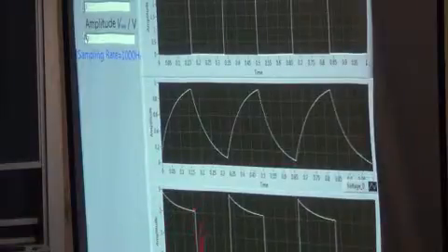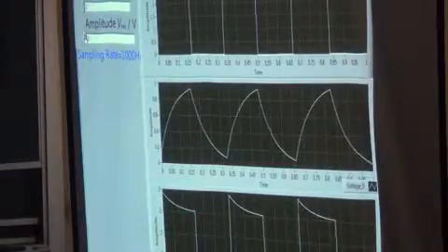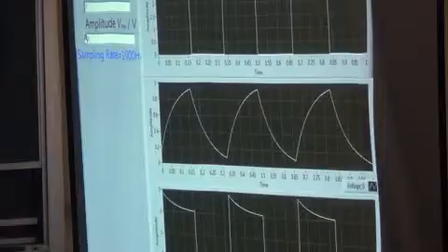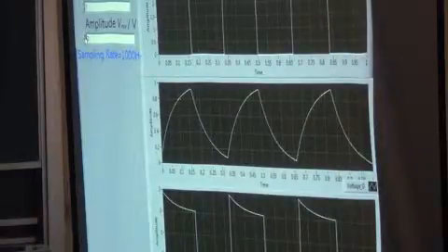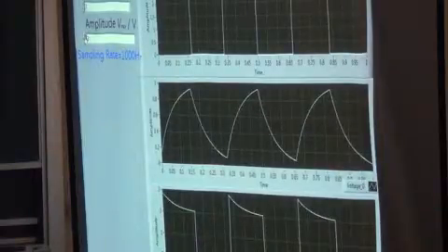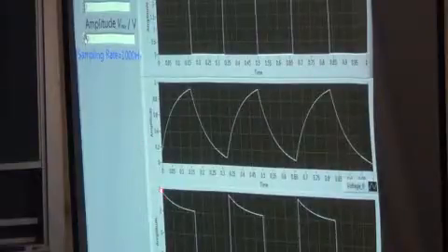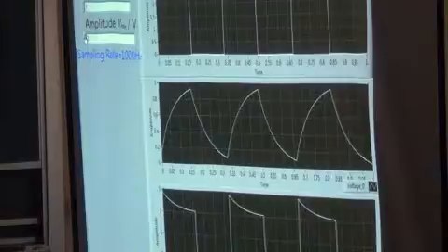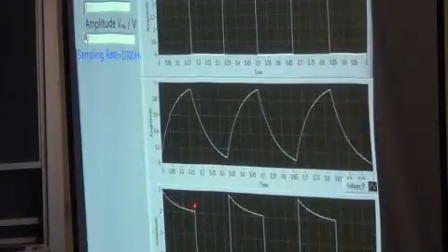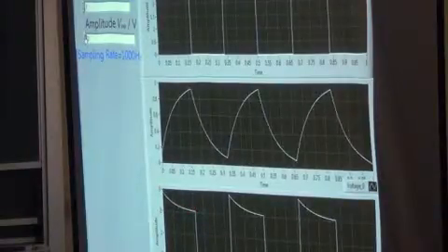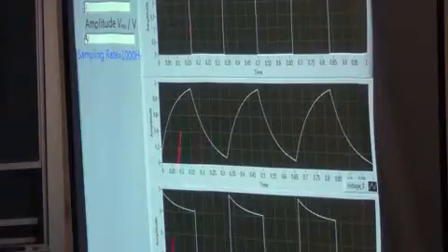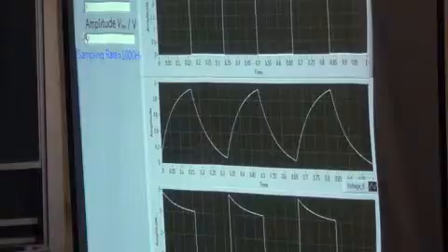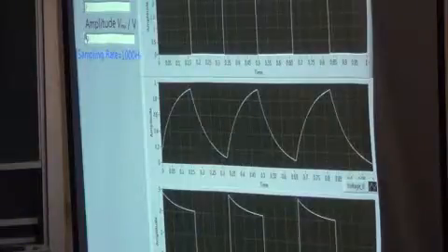This is in fact the current through the circuit, through the resistor. I've plotted the voltage across the resistor, which is proportional to the current through the resistor. Now, initially the current is maximum, and as the capacitor is charged, it builds up its fringe field, the current through the wires decreases, and then as I switch off this pulse, the current reverses its direction and starts flowing in the opposite direction. So this is exactly a nice demonstration of an RC circuit.